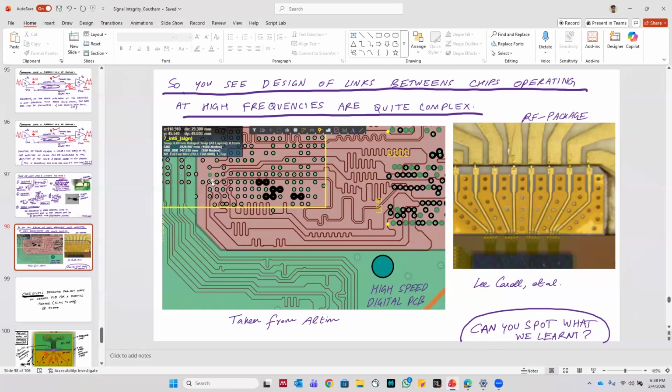A lot of these software tools, for example Altium, which is a common PCB design software, do this automatically for you. It finds the optimal wire design, so it's an optimization problem. We're minimizing the length of every wire while at the same time keeping the length of every wire the same, right? When you do that, this is one of the solutions where, although it looks completely random, it is the best possible situation, with every wire being the minimal length possible while also maintaining the same length between all wires.